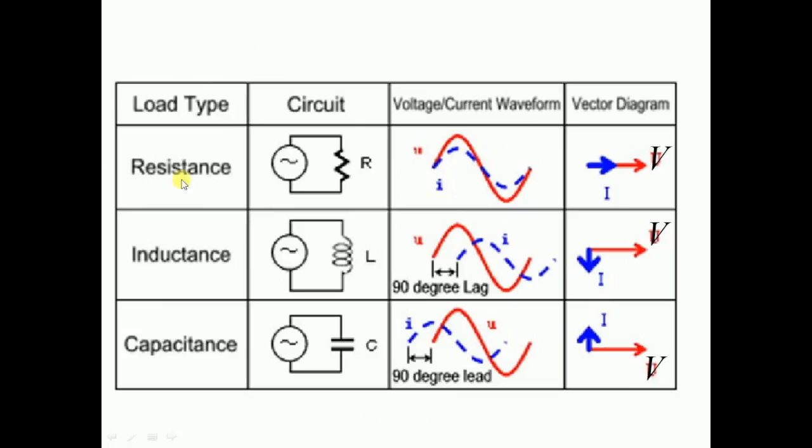Now for pure resistive circuit, we have current in phase with voltage. So here both the arrows are shown in the same direction, and as time rolls they will rotate in anticlockwise way, the way they are plotted here. For pure inductance, current is lagging behind, and this combination as a whole will rotate about the origin, and in capacitance current is ahead by pi by 2.